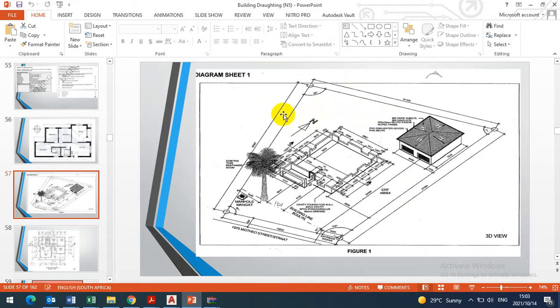When we come to elevations, the north arrow is an important arrow, because when they ask for north elevation, it's this side of the garage. This side is the north view. You'll be looking from there this way. The south is from the arrow side here, where the tree is, will be our south elevation, okay? And the east will be viewing from here, and the west like that. And then if this north arrow is turned the other way, then the north will be down here, the south will be this side of the garage, the east will be here, viewed from here, and the west will be here. So just keep on working with the north arrow.